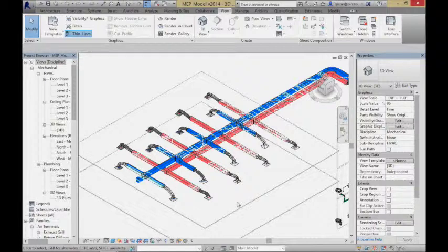Very often, just so you know, in the way of designing things, we often supply the air out near the surfaces. So the outside walls where the big windows are, if we're going to heat a space, we tend to put it out where you're most affected by the external environment, because near those windows, that's where it's going to get cold. It's also where it gets hot. So the conditioned air I often introduce near the outer surfaces that are more affected by the environment. We often pull from the inside, so through the hallway. So you have the fresh air coming to the outside, then pulling back into the center, and it creates a nice flow of the air.